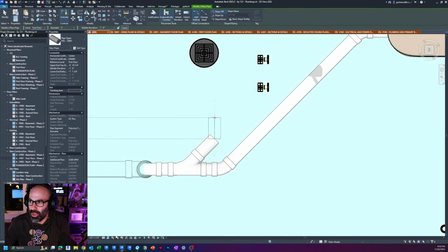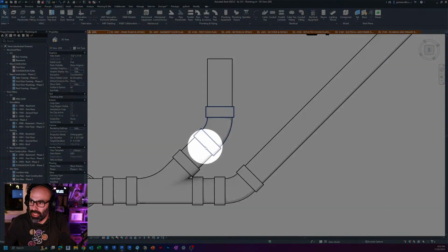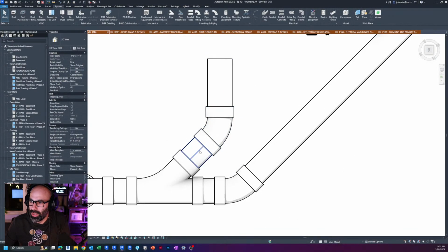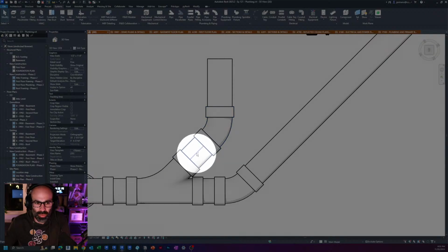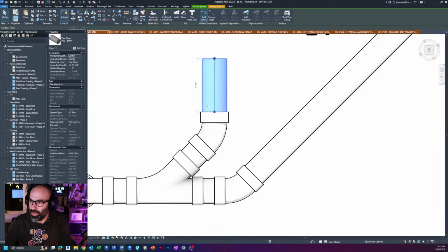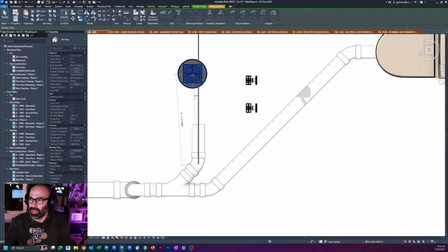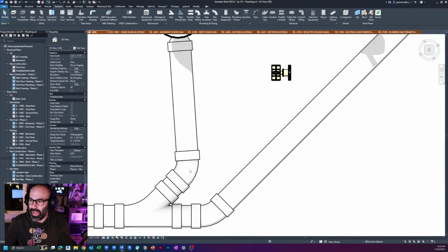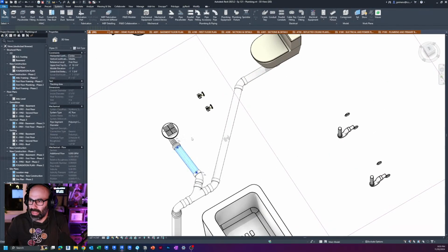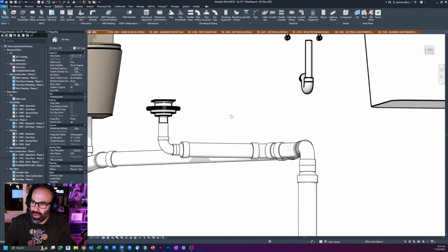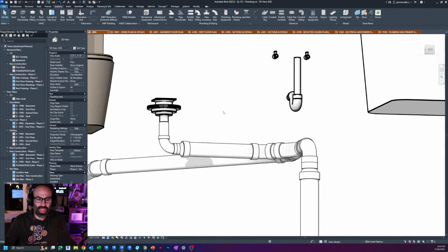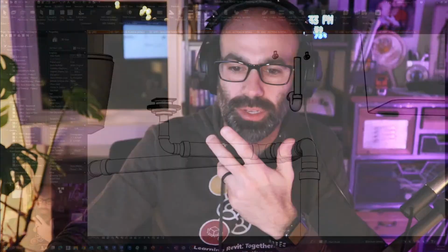The other thing is now if we're going to go on a 45 after this, there's a limitation here. At some point, this pipe sort of disappears. That's when you can start playing with it. I'm just going to nudge it for now just to see what that means to get from here to here. You could see I actually was able to do it like that. You get kind of the idea. Actually, this connector was right, and notice it automatically connected. This is why doing the connectors first is huge. You saw I'm basically just drawing as if I'm drawing walls, but it's doing what I needed it to do, okay?